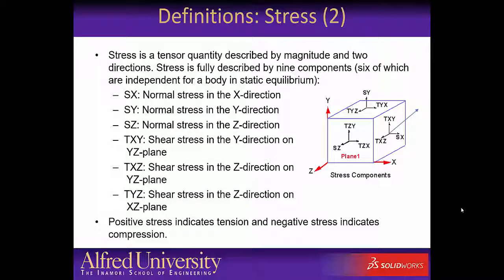We could similarly derive an additional 6 components as shown on the infinitesimal cube. A total of 3 normal stresses, Sx, SY and SZ, and a total of 6 shear components: tau xy, tau yx, tau xz, tau zx, tau yz, and tau zy.